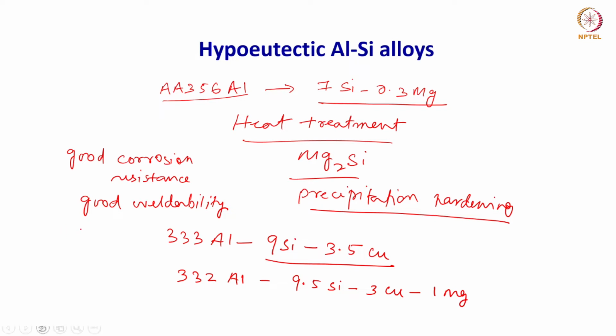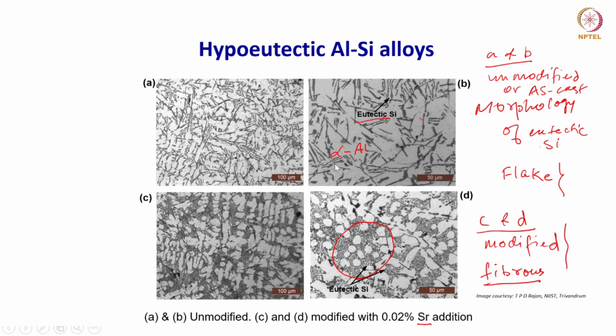And of course, it's a low density light material, with a density less than pure aluminium, because silicon also is a lighter metal. And property wise, there is something to do with this silicon phase that you see over here. This is present like a completely different phase which is distributed all over the place. This will give rise to a particular property which is really very useful for some of the applications that I was mentioning, particularly for the automotive, right?